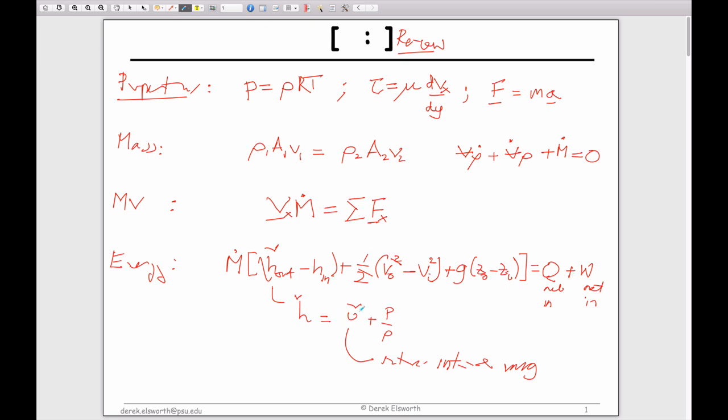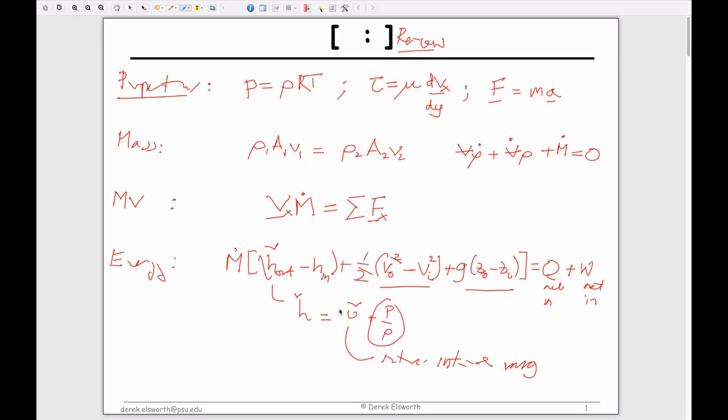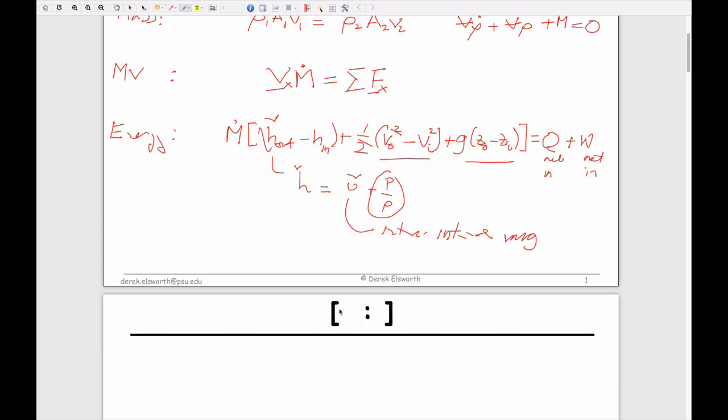And you see that this has the same terms. It's written between in and out, specifically between upstream and downstream, as we have talked about in the past. This is the inertial term in Bernoulli. This is the potential energy term in Bernoulli, and the pressure term in Bernoulli comes in here. But it also has this extra internal energy if you want to do calculations about chemical reactions in systems, and we used it historically in a couple of examples in the videos that you looked at online. Okay, so that's one form of the energy equation.